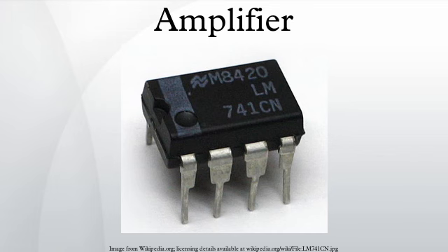The frequency range handled by an amplifier might be specified in terms of bandwidth, or by specifying a frequency response that is within a certain number of decibels between a lower and an upper frequency. Power amplifier classes. Power amplifier circuits are classified as A, B and C for analog designs, and Class D and E for switching designs, based on the proportion of each input cycle during which an amplifying device is passing current.